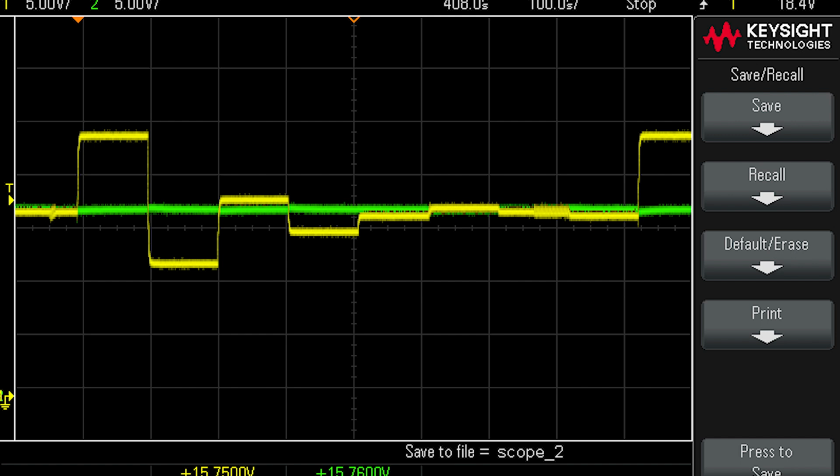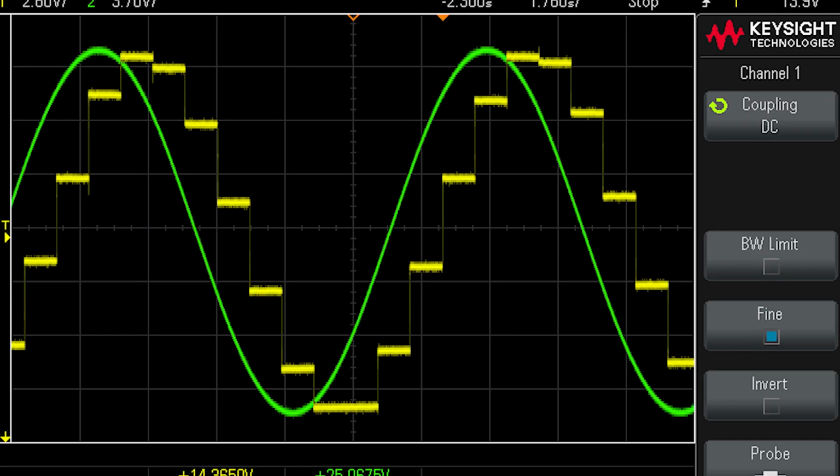To check the actual output of the ADC as an analog value, we can simply run the 7 output bits through another DAC. We can then read the output of this DAC and compare it to the input voltage. As you can see here, we're following a sine wave with the output of the ADC. This produces a discrete representation of this sine wave with many different voltage values.